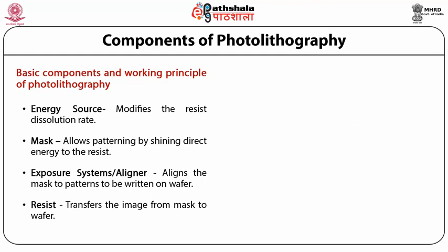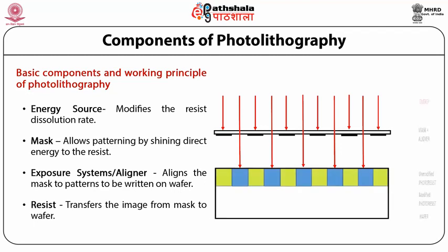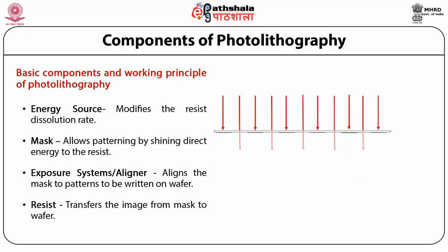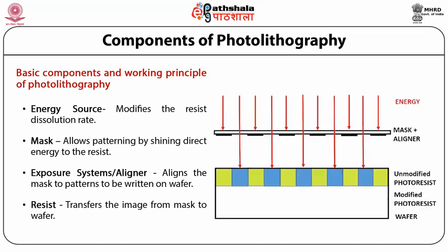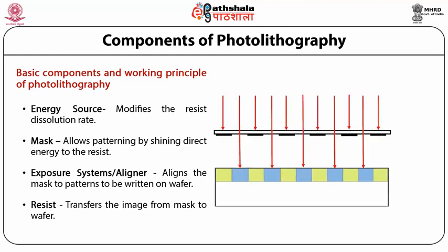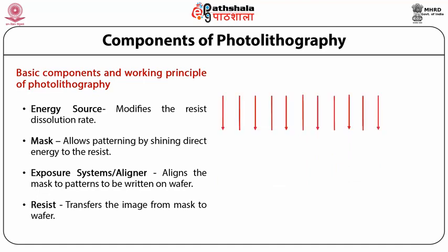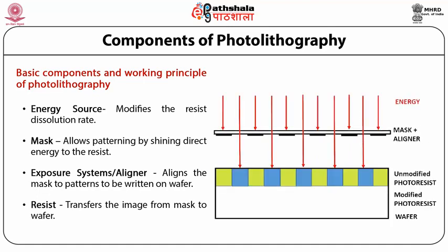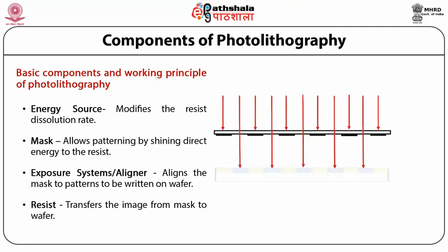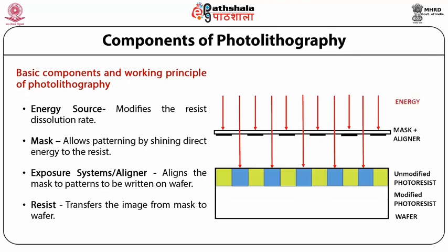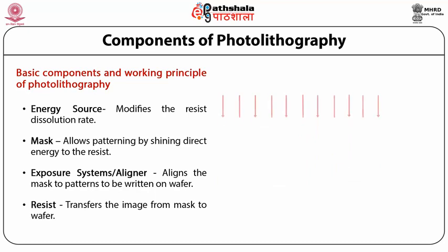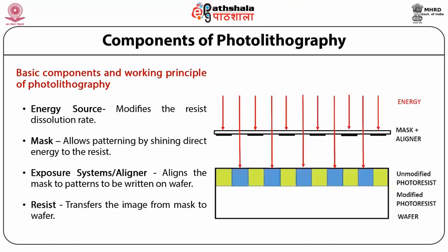A schematic of the photolithography technique is demonstrated in figure 1. Generally, photolithography utilizes a light source that illuminates over an area of larger dimension compared to the dimension of the features to be designed. This requires a photo mask of the same design with the feature sizes to restrict light to pass through and fall on the photoresist on the substrate. The photo mask is the master pattern of the designs that transfer to wafers.